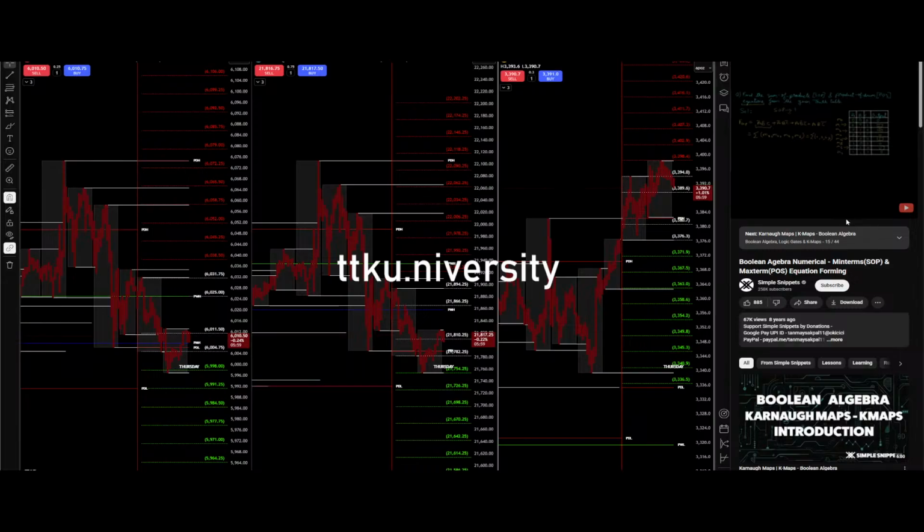So now let's calculate the functional equation of POS. Now POS is associated with the output as 0. So given in the truth table, wherever the output is 0, we need to consider those variables for formulating the equation of POS. So this would be A or B or C would be our first term. Since we need 0 as the output and we have all A, B and C 0 in this case, so we don't need to take complement of any of these values.